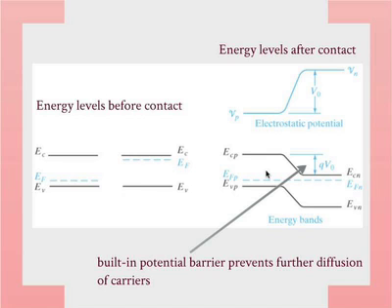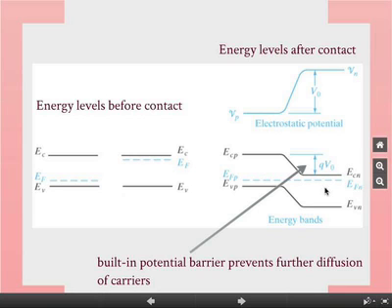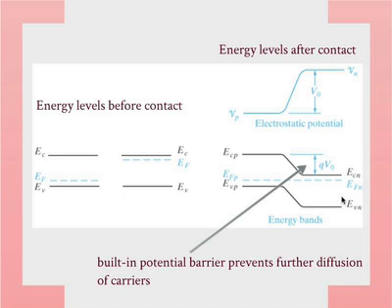Okay? This sort of logic will become very natural to you because all the analysis of devices has to be done this way. Now let's think about electrons. Okay? There are lots of electrons on this side. Very few electrons on this side. Of course, electrons will move from right to left. Right? This way. So the built-in field has to prevent that motion, which means that the field also has to point in the same direction.